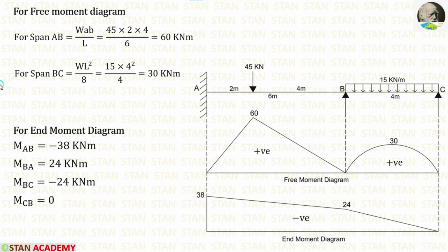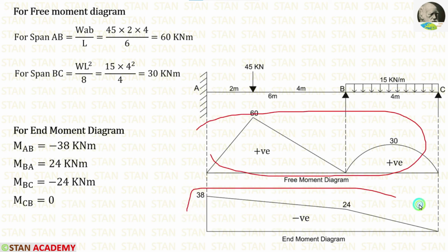Now we are going to draw the bending moment diagram. For drawing the bending moment diagram, first we have to make the free moment diagram, then end moment diagram, then we have to combine both of them to make bending moment diagram.